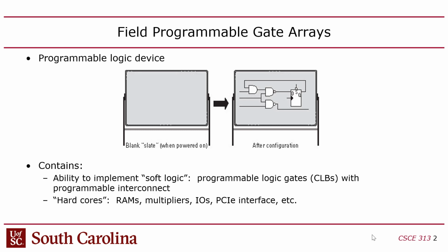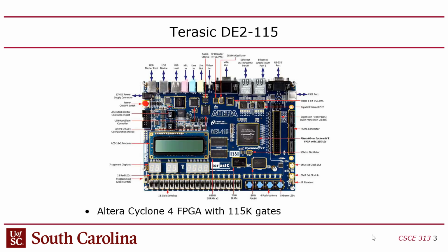These are FPGAs that have been prefabricated, but they can mimic an ASIC essentially, but they run slower. So that's an FPGA, and we're using these FPGA boards. An FPGA by itself is useless, even if you can configure it, because it has to be connected to stuff. It has to be wired into peripherals. The reason we chose this board is because it's got a ton of peripherals, and it's almost indestructible.